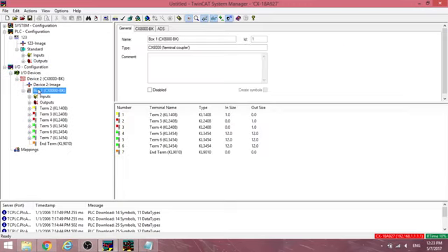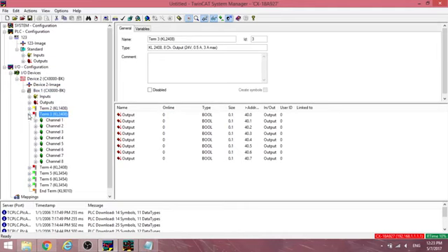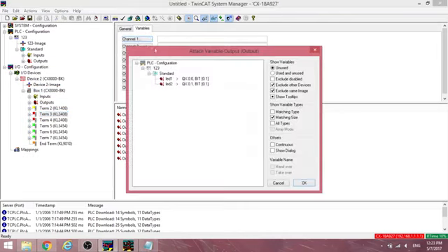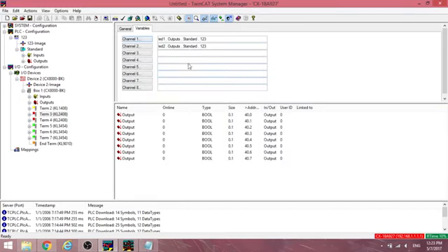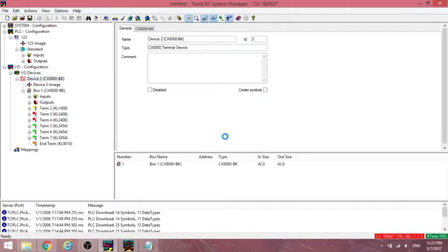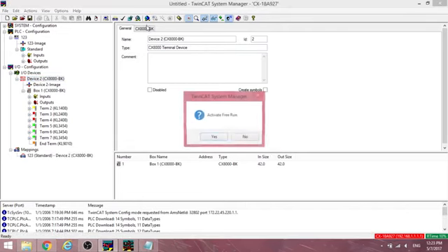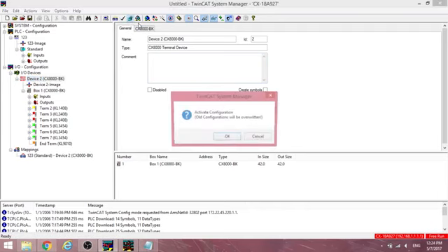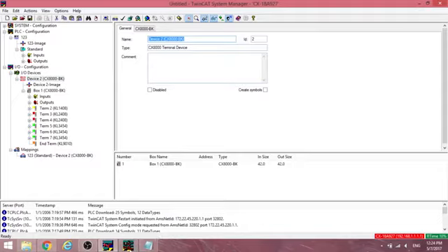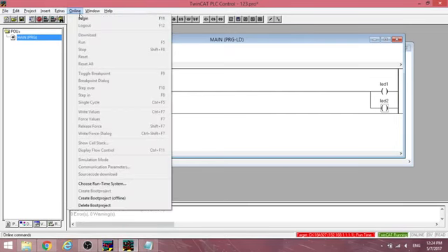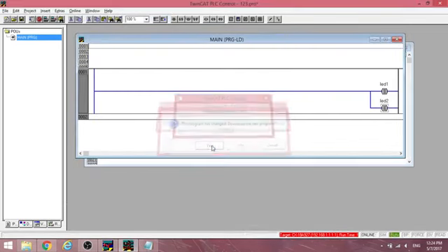address. Under I/O devices, find the Digital Input and Output modules of the PLC, and under the Variable tab, bind the output variables to the channels. Restart the System Manager in config mode. Head back to the PLC control, go online and run the program again. The corresponding lights on the PLC should light up.